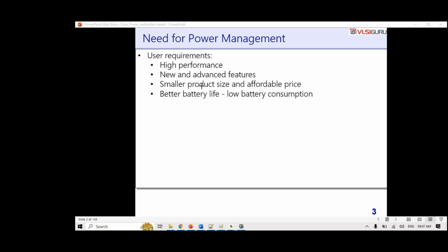You would know, right? You have got the drain, source, the oxide, and on that you have the gate. As you reduce this, the oxide width also needs to be reduced, which leads to some kind of tunneling, and that leads to gate leakage also. There are four types of leakages which we'll talk about.